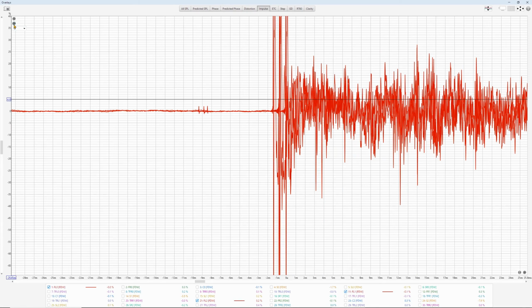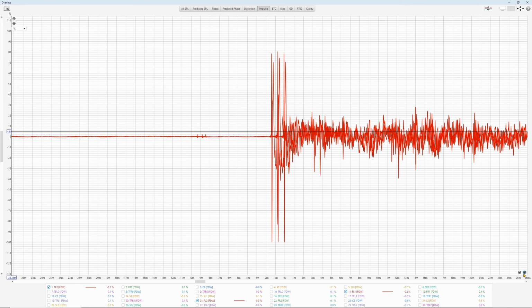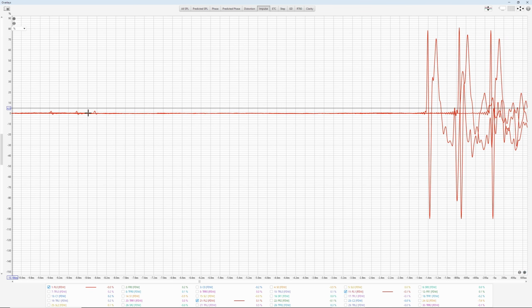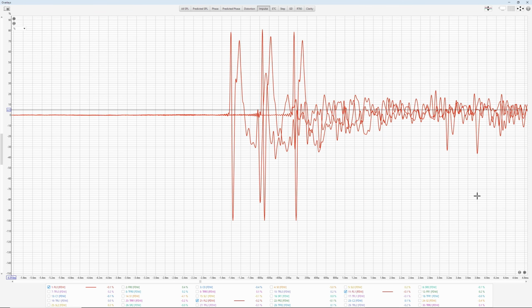Let's make this visible; interestingly, they're all the same red color. Here are my chirps because of crosstalk in my system, but I'm not going to be using them this time to measure speaker distances, so don't worry if you don't see the chirps. Now the one in the middle is front left, and the one on the left, this is FL1, is somewhere around 22 centimeters to the left of the center position, and the one on the right is again very similar, around 23. This doesn't have to be exactly the same, but it should be kind of symmetrical for the average responses to make more sense in the later stages of the correction.